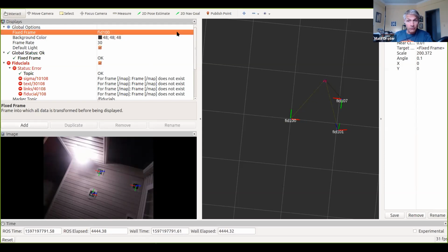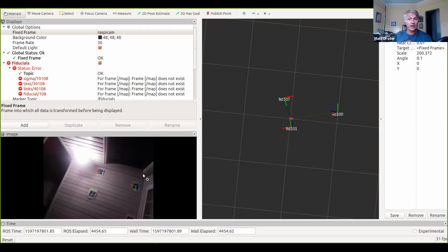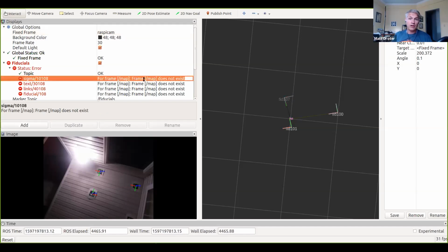So you're pretty close in the fact that you've got the SLAM working. So did I miss something? No, you just have to extend your transform world. You have to have a map frame, and your map has an origin, and then since your fiducials are fixed in your world, there's a specific distance from your origin to each one of those fiducials.